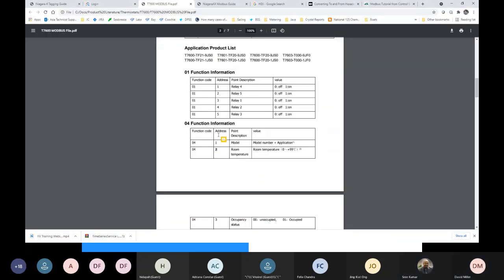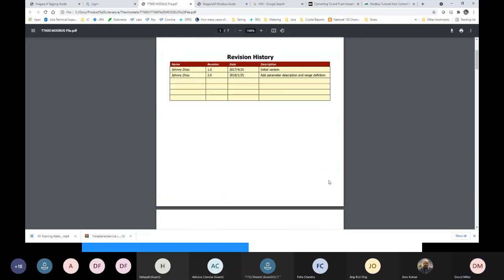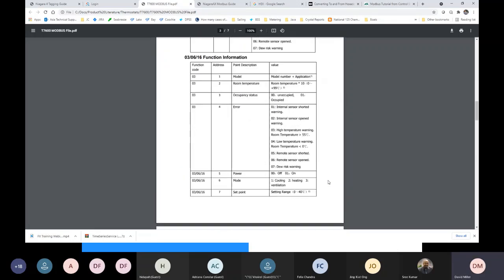It's every time you do a Modbus integration, every time you look at a Modbus table, there is always a doubt as to whether that is 1 or 0. Whether it's starting at 1 or is it starting at 0. Right. Okay, so that's just a fact of life with Modbus. And you might be able to read something here that tells you that.